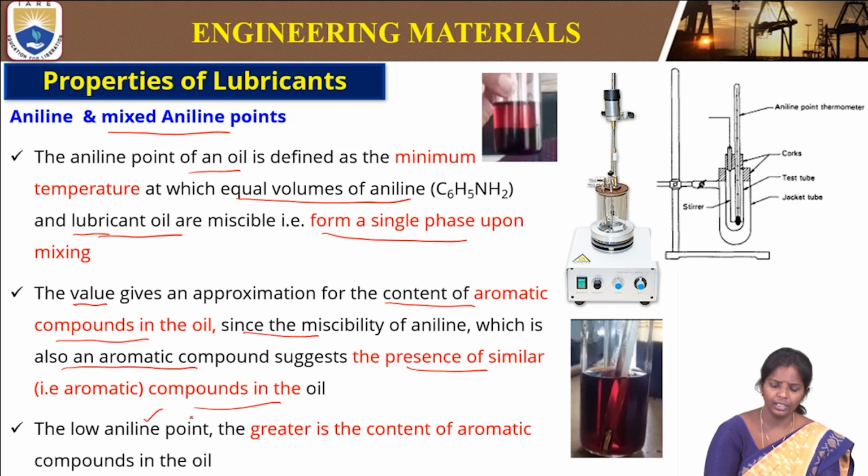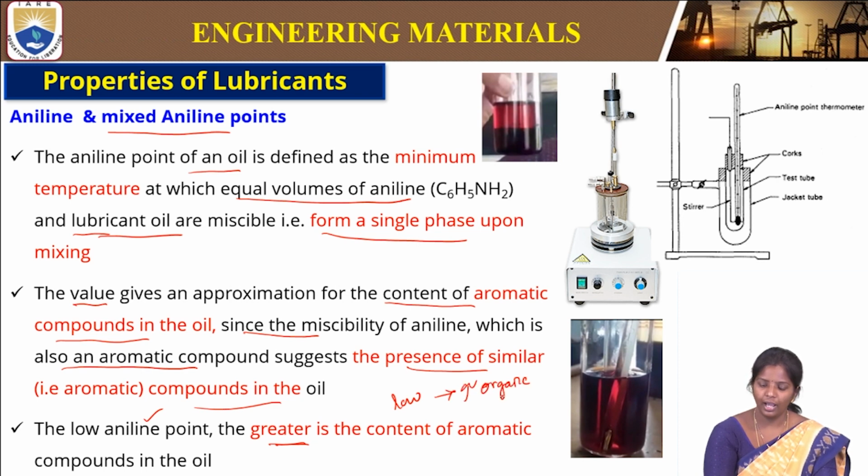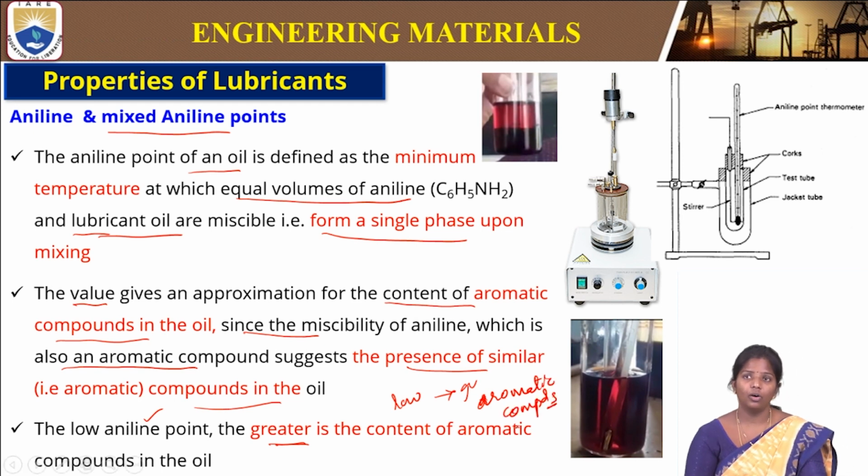So the lower the aniline point, the greater is the content of the aromatic compounds. If it is low, then it will have high organic or aromatic compounds. So that is how it is determined or interpreted.